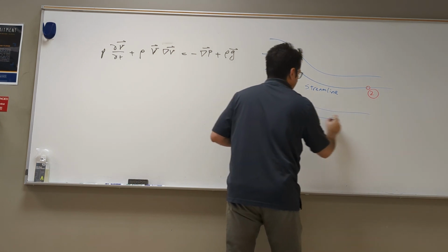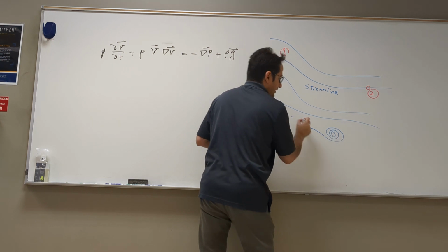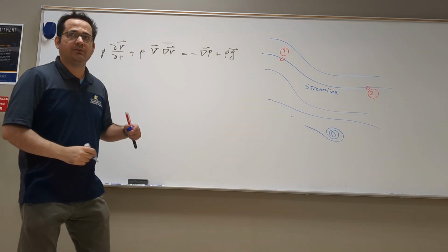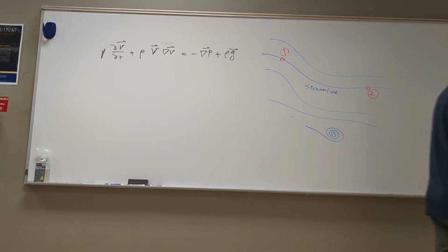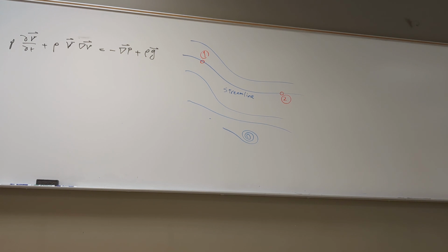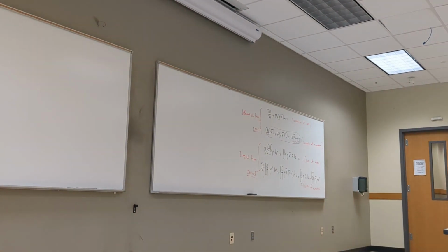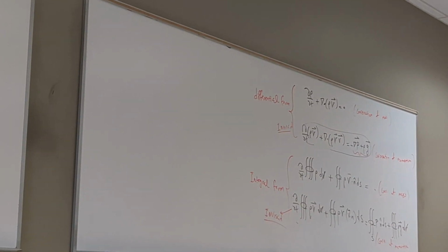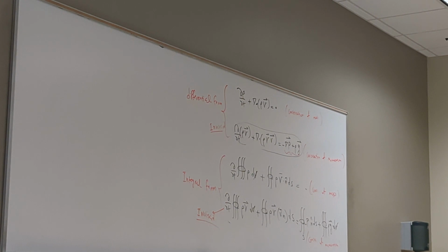If the flow goes this way, you may have chaotic, turbulent behavior. But if in some region there is no friction, which is conservation of momentum frictionless, inviscid, no chaotic behavior, the streamline goes through this point, and also if this streamline is constant versus time, that means this pattern is not going to change.